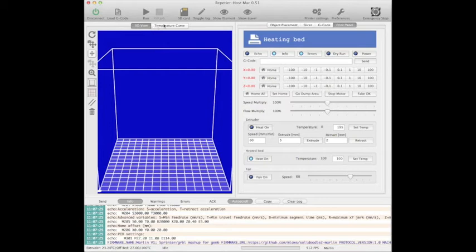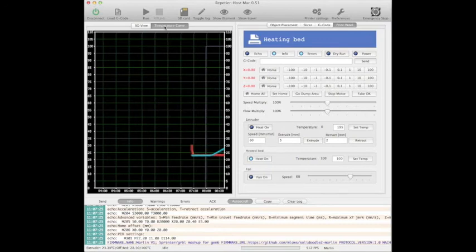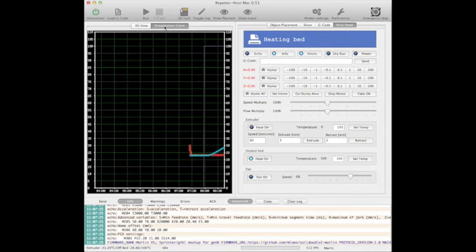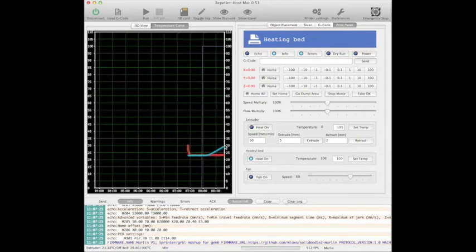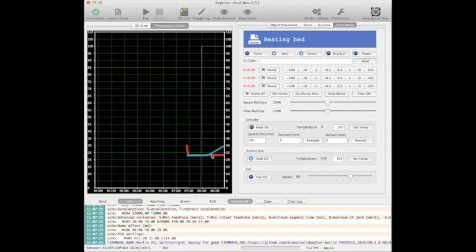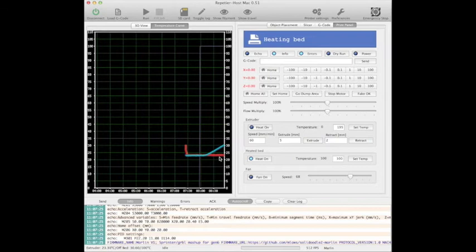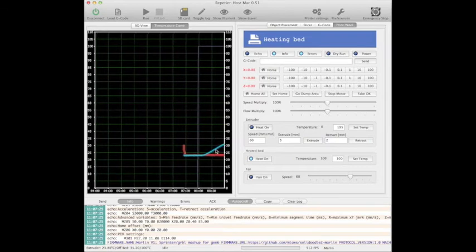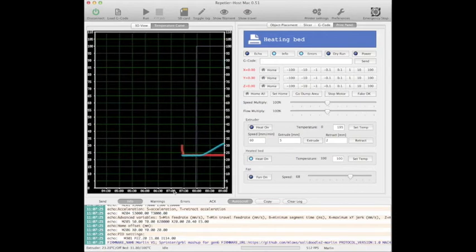In the 3D view area, one of the other options we have here in the print panel is the temperature curve. This is very useful to get a feel for what's happening and give you an idea, I suppose, as well, of how long it's going to take to print. You can sort of see it's just slowly warming its way up there. The blue one here is the print bed, the red one is the extruder. And I'm really hoping that that is blue. I'm colorblind and I'm now thinking, is that green? But anyway, you get the feel for it.